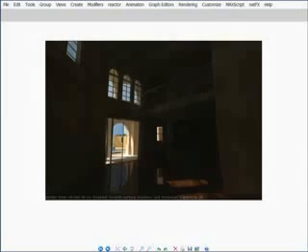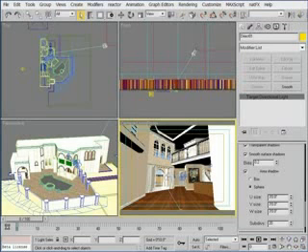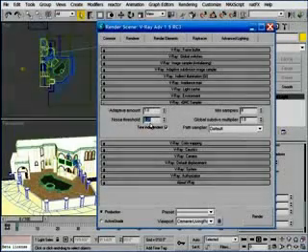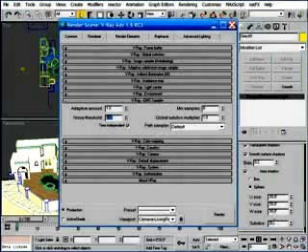One more thing I want to point out, just like all subdivision settings anywhere in VRay, whether it's for material reflections or refractions, blurry reflections or refractions, for light shadows, you can only go so far with the shadow subdivision or whatever subdivision you're trying to adjust. So if you don't have the noise threshold set low enough inside the QMC sampler rollout, the subdivision value that you specify for any given setting won't make any difference.